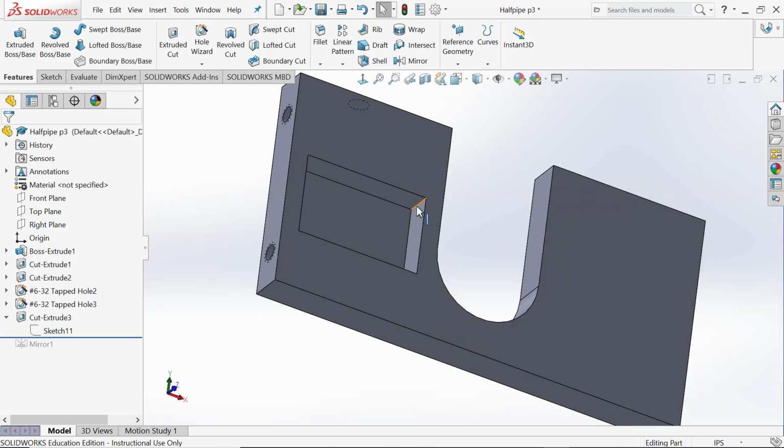Anyway, the reason we did this was because generally when you're manufacturing a part of this type, you use a tool that is cylindrical with cutting blades around the outside of it to make this opening in the flat part. It's called an end mill. And so when you plunge down into the surface like this and move around, when you get to a corner, it's actually going to leave a round corner rather than a sharp corner.